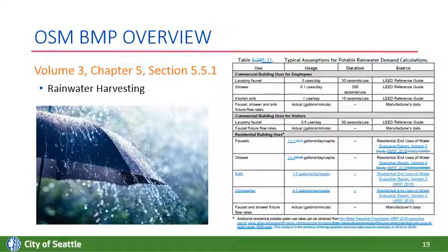There are some updated site considerations. The on-site list approach has been updated because you have the category 4 approach and the category 2. The on-site performance standard modeling approach has been updated, and assumptions for determining rainwater demand have been updated. Added is a BMP sizing approach for category 2 and 4 on the on-site list. And this table here is the updated assumptions table that was mentioned.